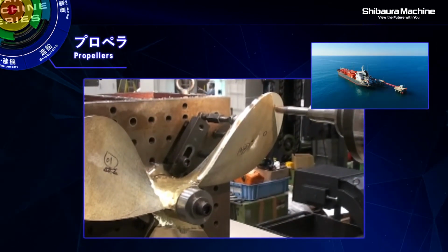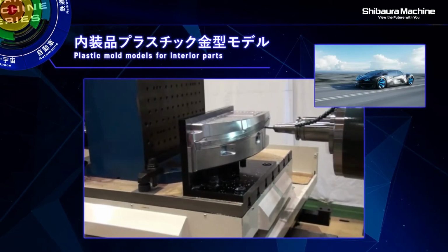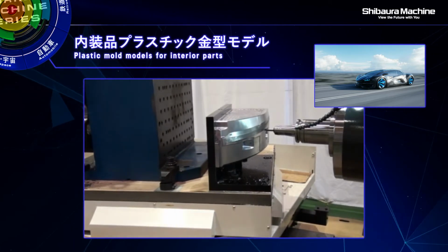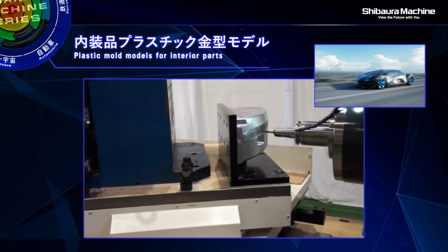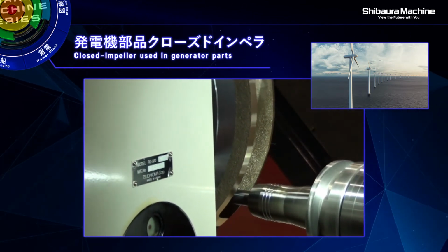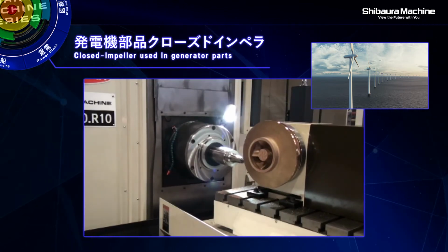In shipbuilding, it is possible to process fine shapes such as propellers for ships. In automobiles, it is the processing of plastic mold models for interior parts. In simultaneous 4-axis processing for mold machining, in addition to the rotary milling function, tooltip point control and shape function are used for processing. For power generation, it is the processing of closed impeller models used in pumps and generator parts, which energize liquids and gases. You can also process intricate shapes of wings.